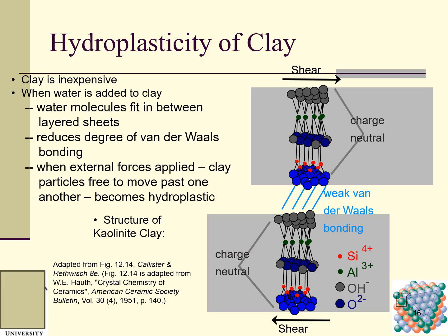When water is added to clay, water molecules fit in between the layered sheets and reduce the degree of van der Waals bonding. Van der Waals bonding is between the layers, which is kind of weak. When external forces are applied, clay particles are free to move past one another and become hydroplastic.